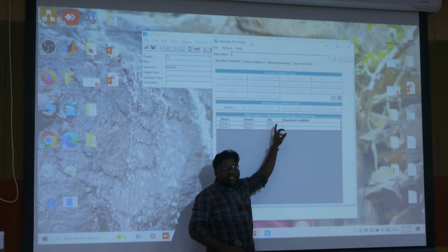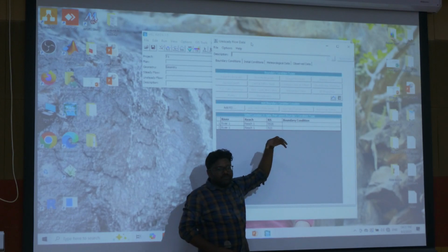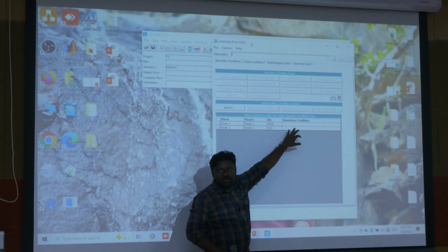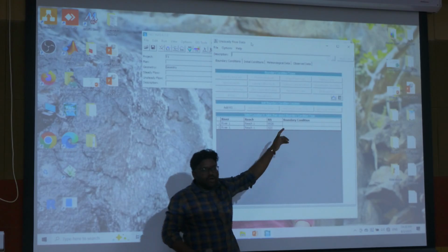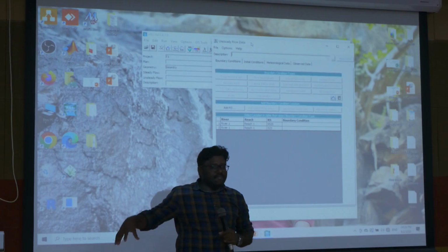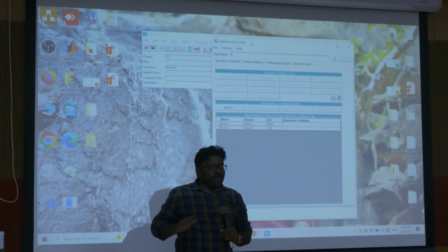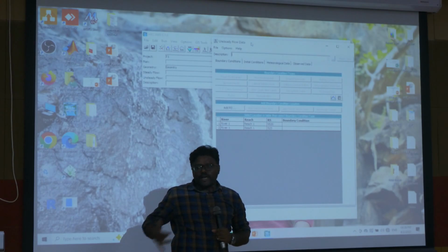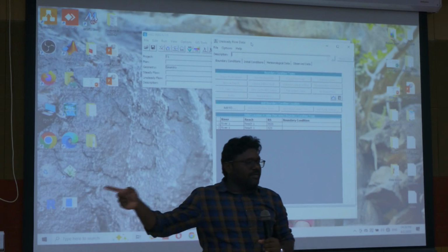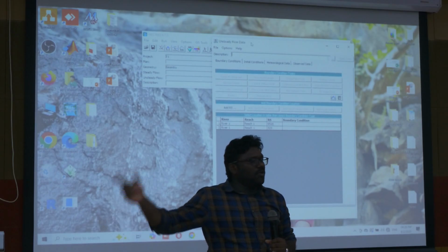Our upstream boundary condition was our upstream flow, which was coming from HEC-RAS. But we don't know the water level at the downstream, right? So we are assuming that at the downstream the flow was uniform flow, so it is following the normal depth concept. There, to identify the Q we are giving the friction slope value.